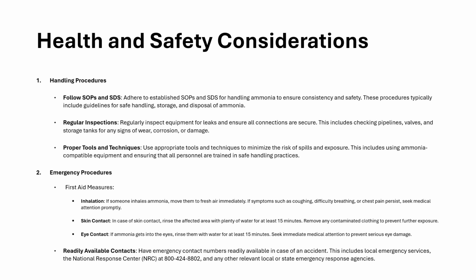In case of skin contact, rinse the affected area with plenty of water for at least 15 minutes. Remove any contaminated clothing to prevent further exposure. If ammonia gets into the eyes, rinse them with water for at least 15 minutes. Seek immediate medical attention to prevent serious eye damage.